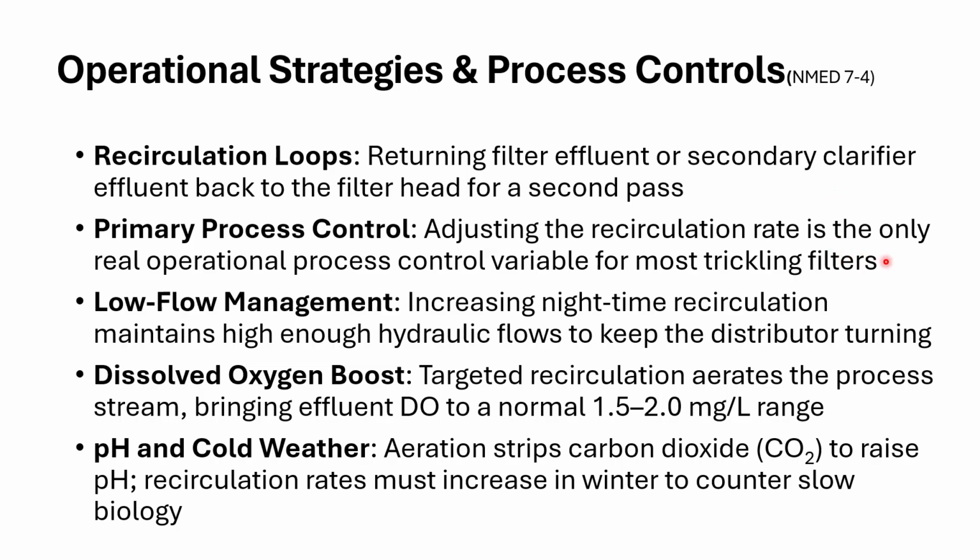Okay. So here's something to think about, though. Pretty important concept. That recirculation rate, for a trickling filter, is really the big and only way we can control the process. We can control the recirc rate. Okay, that's a heck of a test question for a level 3 or level 4 operator. What do we do? How do we control it? We can either decrease or increase that rate.